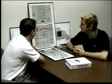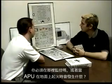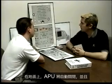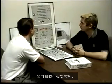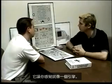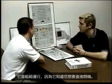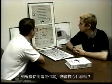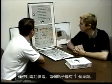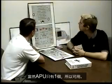You're on the ground, the APU's running, and it detects a fire. Do you have to be there to monitor it, or what occurs when APU fire on the ground? No, on the ground, the APU will automatically shut down, and the fire sequence will take place. What about an APU fire in flight? No, it'll be just like an engine, it'll continue to run because it knows that you want to direct the shutdown. Anything that you're concerned with if you're on battery power only? Battery power only, you only have Agent 1 for each of the bottles. Of course, APU only has one, so that one's available.